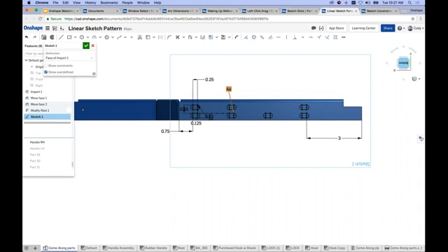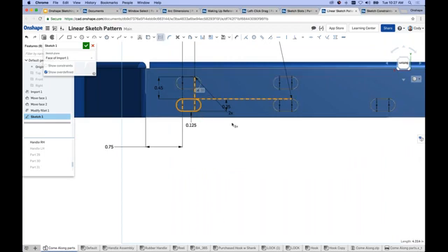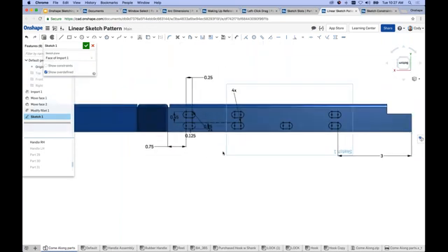What if you just turned the geometry to construction geometry of a single pattern instance? Good question. It affects only that instance. It does not go downstream, so to speak, right? So the pattern instance does not update. Now, I'm fairly certain if you pattern construction geometry to begin with, you will get construction geometry, but it doesn't update, so to speak. Can you save the instances but release them from control so you can randomly place them?